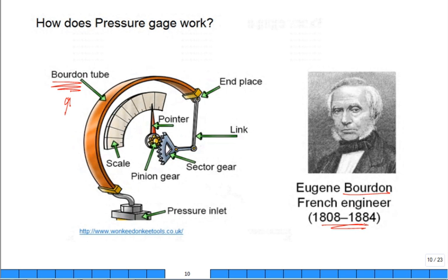You could just take the plastic cover off. This is for refrigerant applications. So you would hook up the hose and you'd put the refrigerant and you'd sense the pressure of the refrigerant there. But I could take it apart, pull it out, take the back case off. And what do I have? A C-shaped. Let me see if I can do this with the dot camera, because there's so many students. What do I have? C-shaped Bourdon tube. And so what happens is it's connected through the linkages, and if you take your fingers and just bend it just a little bit, can you see the action? And then over here, you can see the action.